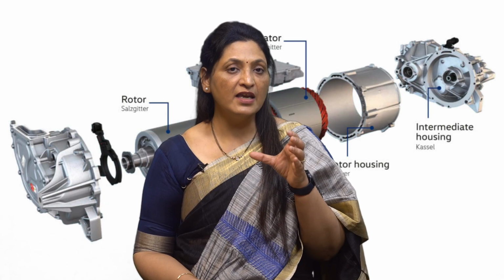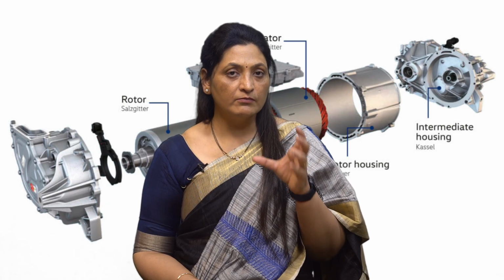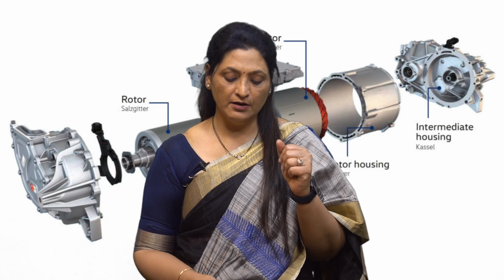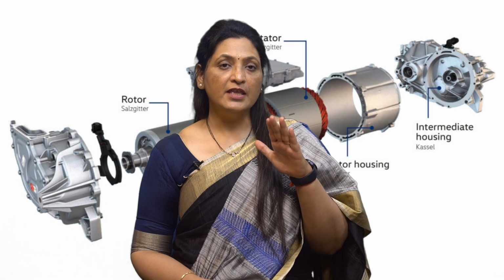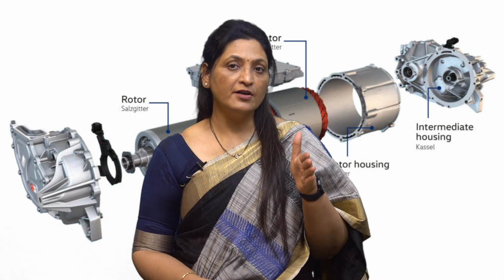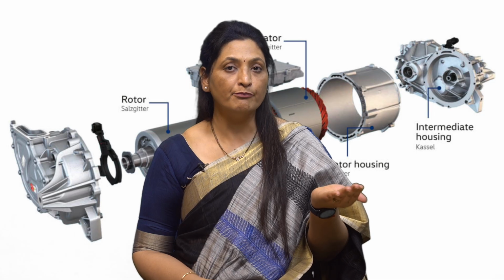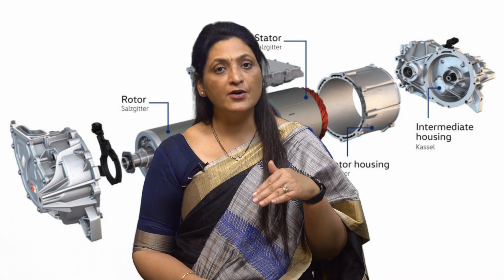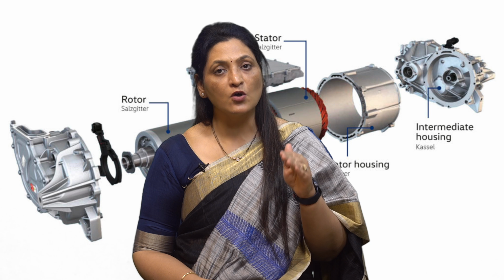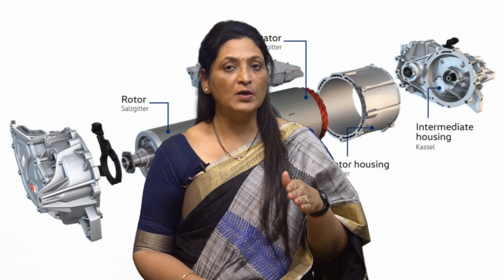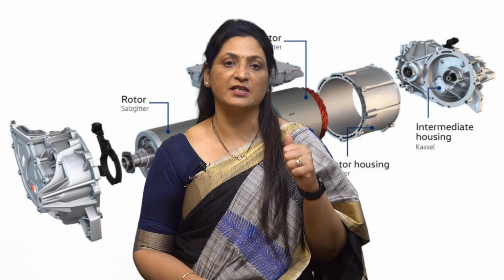This is a very important process which has to be taken care of while driving the electric drives. In this process, energy is stored during the interval of light load and is given out during the interval of peak load. Thus, the power drawn from the supply mains remains almost constant. The most common method of load equalization is the use of flywheels.